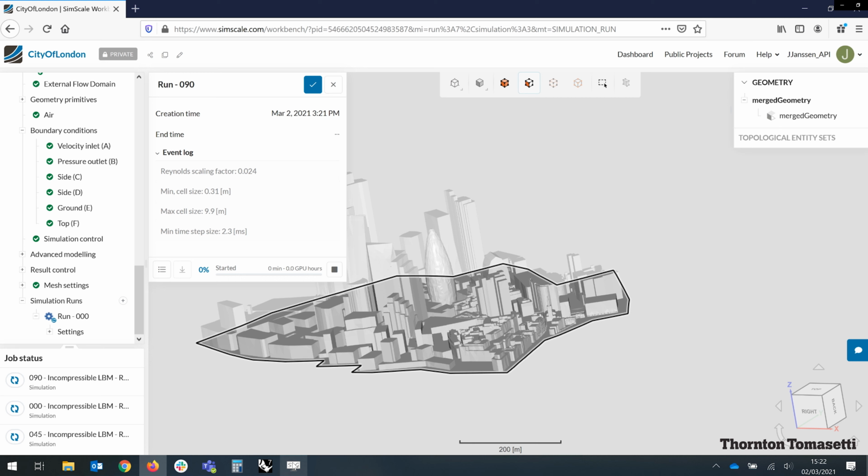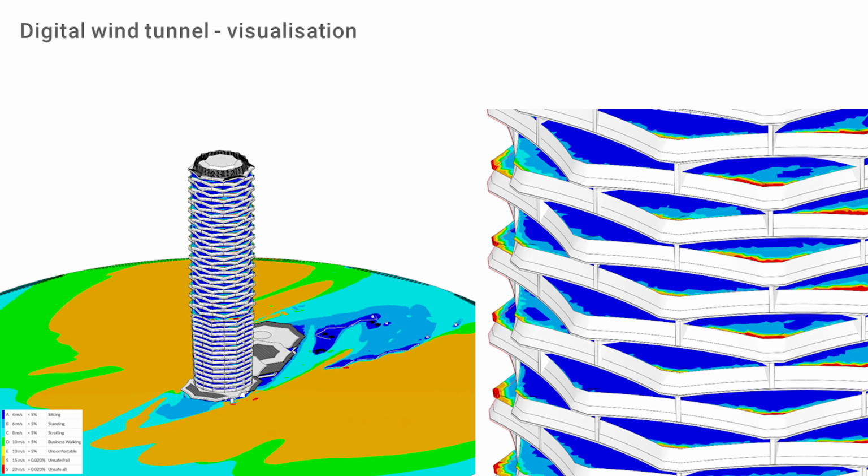And we've basically hooked this up with SimScale mainly because of the solver, where you can almost throw in any geometry and it basically runs automatically. The other thing is it's GPU based, so it's lightning fast and transient. So a simulation of this, for a big domain, is probably just taking 2 hours. For a single building, it might be half an hour or so. And then you have your results back, pulling it back into Rhino. And then you can use that for visualization. So for instance, comfort on the ground and on balconies of this tower.